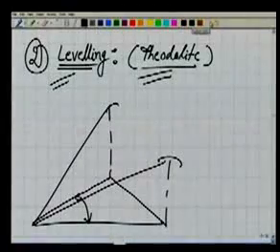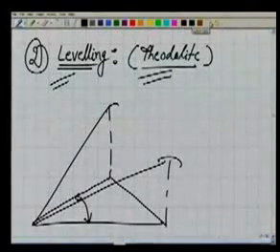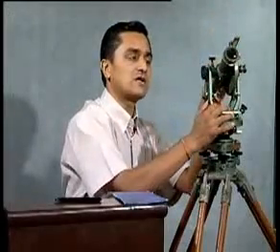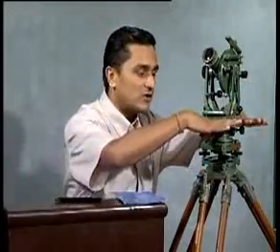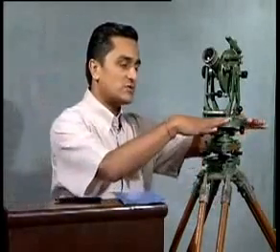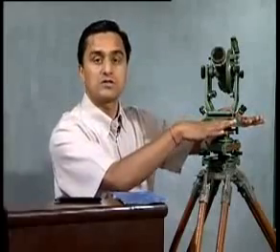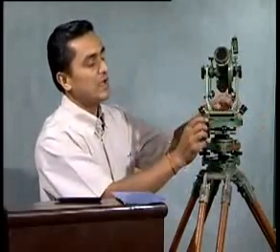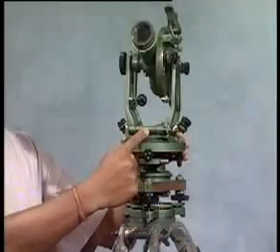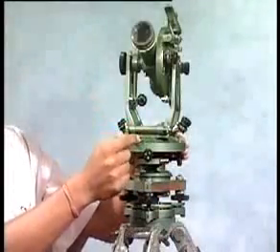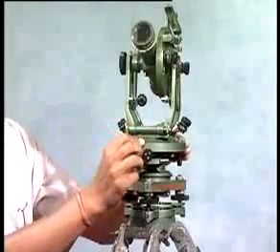So if there are 2 objects here, for this theodolite, one here, the theodolite may bisect like this and bisect like this. We are interested in the corresponding angle at the horizontal plane, the projected angle on the horizontal plane. So our measurement, or the graduated ring, has to be horizontal for this purpose. Now how to ensure it? In order to do that, we have a bubble tube here, and we have seen what the bubble tube is, what we want to achieve using the bubble tube.